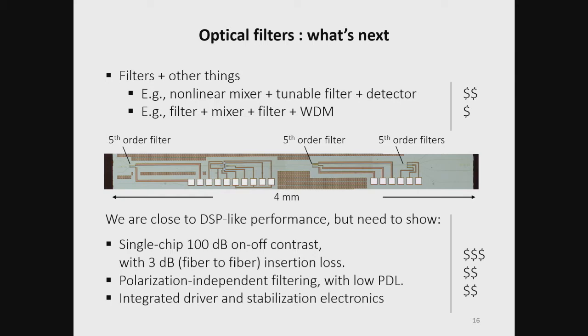Also, these are polarization dependent. Silicon waveguides tend to be TE guiding or TM guiding, typically not both. If you have low PDL, can you make a microring that's sort of robust to fabrication? Or does it randomly go from TE to TM and mess up your transmission spectrum? So there's something called polarization diversity, in that you make 2 circuits for the price of 1 and hopefully balance your responses, but that takes time and effort and some fabrication.